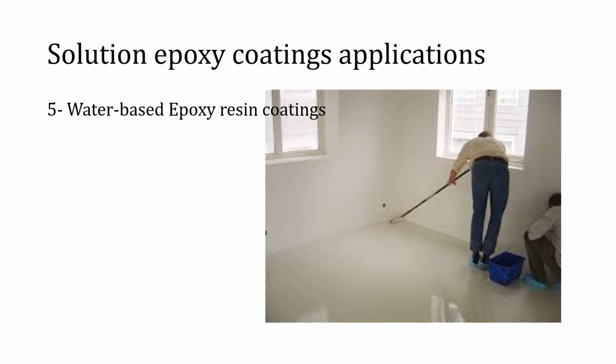For dip coating applications, drainage of the emulsion from the object as soon as it is removed from the emulsion determines the film thickness and its quality. Even drainage is needed for an even coverage and to ensure the quality of the film formed. In the spraying application, the formation of fine droplets in the emulsion is crucial and it is dependent on the rheological properties of the emulsion, as large droplets can splash where they hit, which consequently results in a more or less grainy surface and finally a coating with imperfect specular reflections.